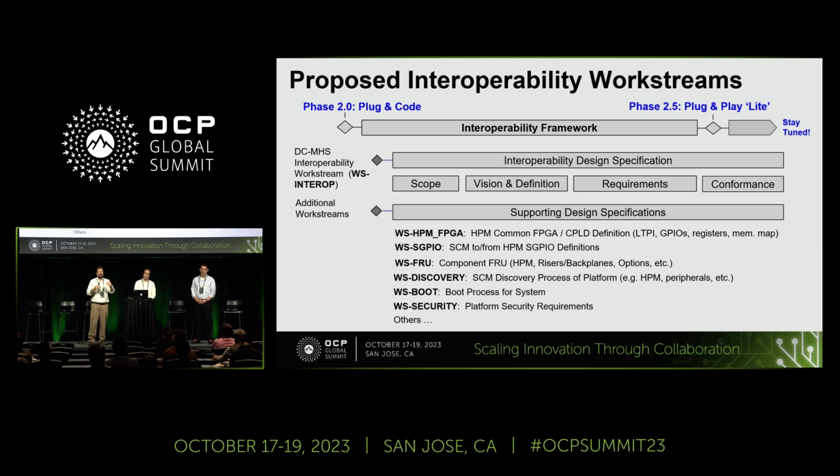But what we actually envision is adding additional multi-records to provide self-describing JSON-formatted data, so that firmware can look at that and say, oh, I understand the topology. That's great, and you would be carrying that in your FRU. In the spec we have today, it's basically just a table of contents and headers and a description of what's in there. But as the work stream starts up, we're going to start putting in those ideas, and then hopefully get community input as it proceeds down the path to 0.3, 0.5, et cetera.